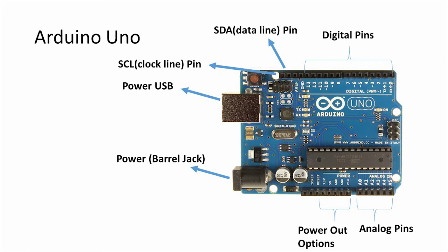We will be using these pins to communicate with the Bluetooth module. The SCL and SDA pins help with communicating with sensors that need to take data during specific time periods. We will use these to communicate with the current sensor.